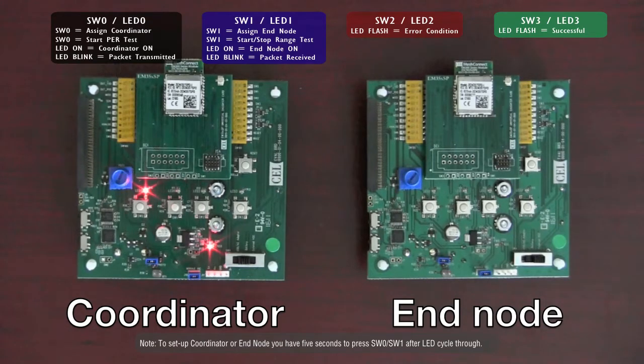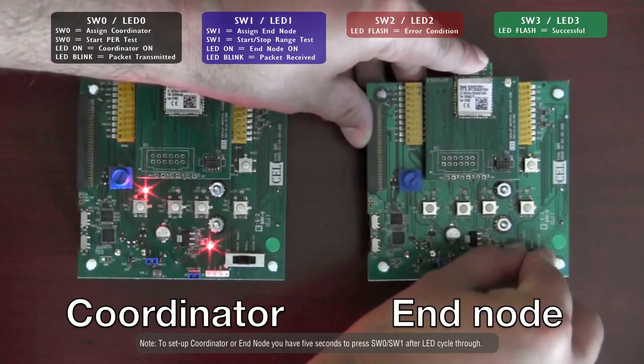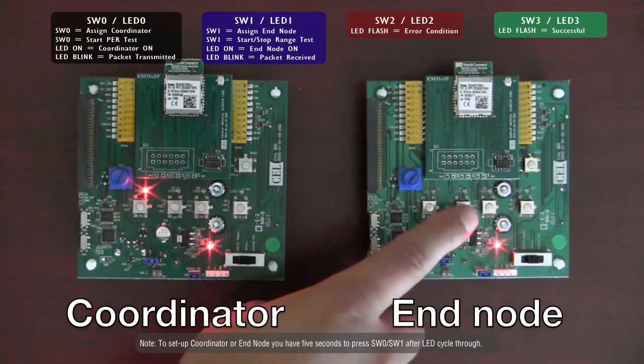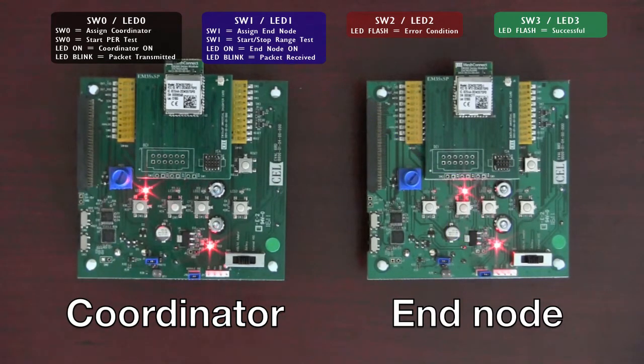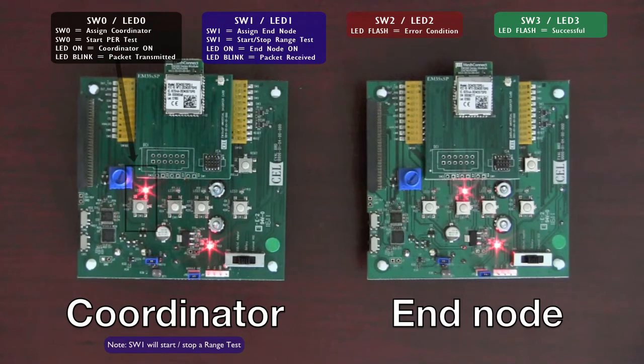Now that we have the coordinator established, we will power on the end node by sliding the power switch to the middle position and allowing the LED lights to cycle again. On the end node, we will press SW1. Once the LED light illuminates, it has found and joined the network. To begin the range test, we will go back to the coordinator board and press and release SW1. The range test is running.